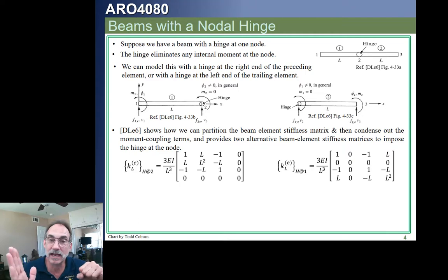Normally, it's that rotation that gives it the moment at the second node. By eliminating the rotation out of that stiffness matrix, we're not going to couple the moment and rotation at all. That allows us to calculate the rotation from other parts of the system of equations and then back solve for the rotation at the node we need.